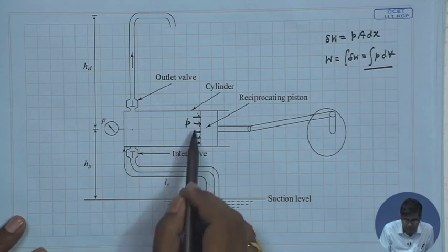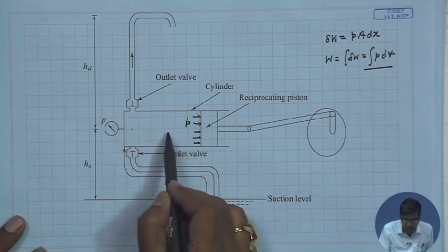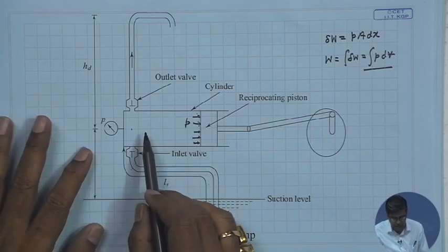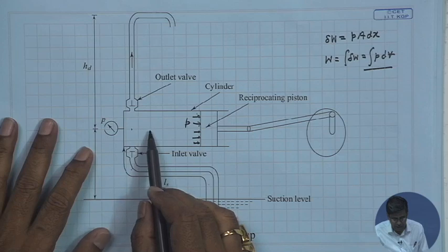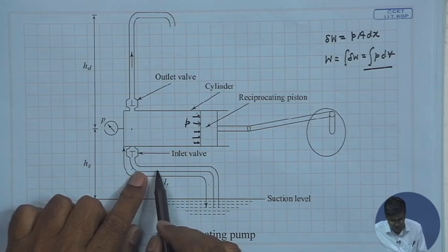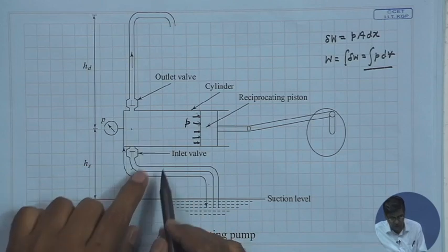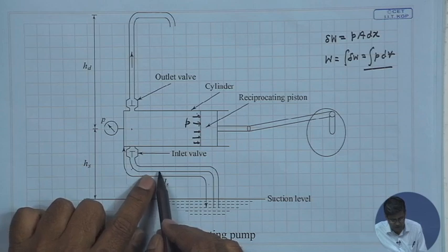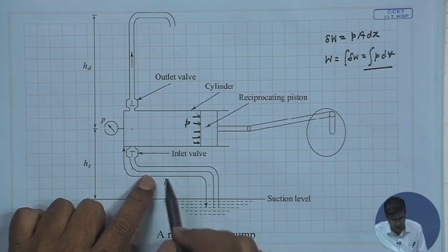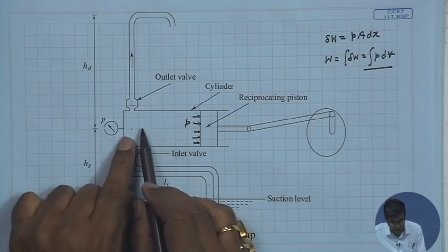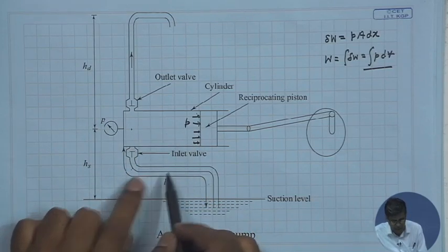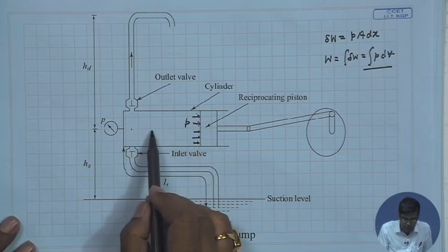in cross sectional area. The liquid will be moving with the same velocity and acceleration as the piston in the cylinder, and at any instant of time the liquid velocity and acceleration in the cylinder and in the pipeline will be related by their cross sectional areas. So, the liquid velocity and acceleration in the pipeline will be more than in the cylinder because of the lower cross sectional area of the pipeline. Finally, the liquid velocity and acceleration both in the cylinder and the pipeline depend upon the piston velocity. So, initially it provides an acceleration.